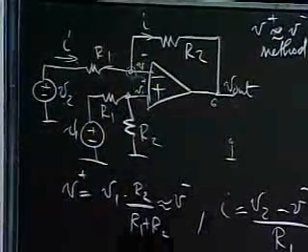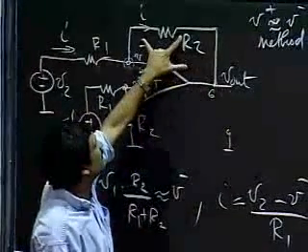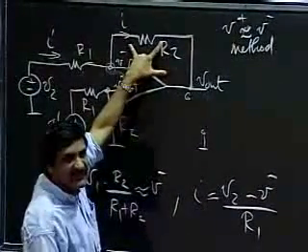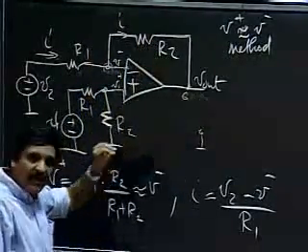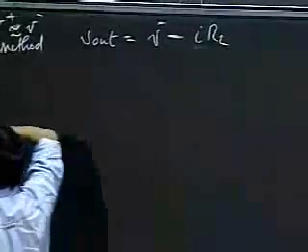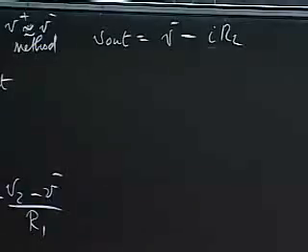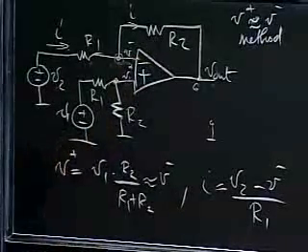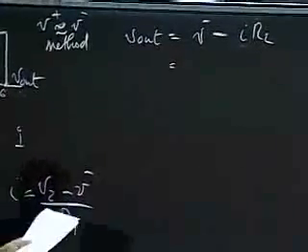One thing to be very cautious about, I'll tell you right now, is that the output here relates to the inversion of the voltage across this resistor R2. Be very, very careful: if I have a voltage across this resistor here, that impacts V out with a minus sign attached to it. Notice that IR2 is the voltage across R2, and V out relates to the negative of that. That's one of the commonest silly mistakes I've seen people make in solving problems like this.